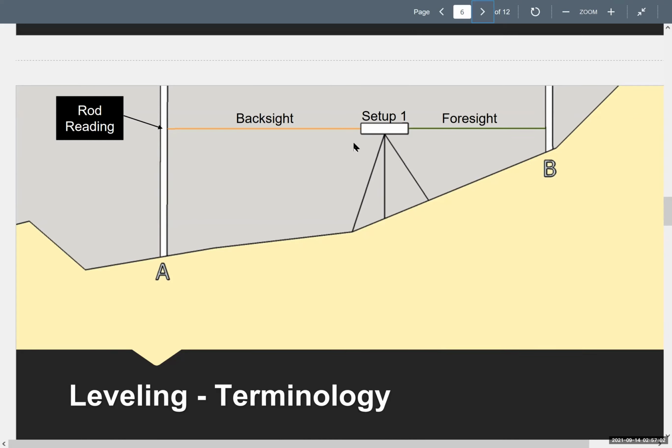And those of you who are in the room, does it make sense to be here where I can see both my points really clearly, with a short horizontal angle? Where if I go over here and I'm in between, I gotta look there and then I gotta look there. No point. You always find a place midway between the two, but get in a position that you can see all your points. Another important reason for seeing all the points is you want to make sure that we're not cutting down any trees to do surveying. So we want to be in positions where we're not blocked by anything.